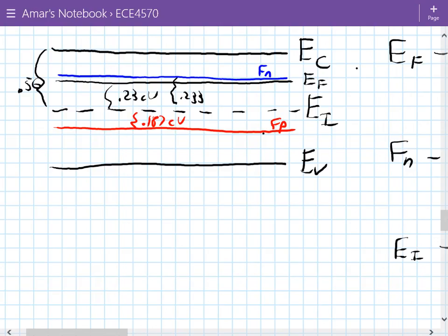What this diagram suggests is that the hole concentration changed a great deal. The hole concentration is below Ei, so there's a larger number of holes than the intrinsic hole concentration, which is 1.5 times 10 to the 10. The many electrons are also present, but not much compared to what there was initially. EF represents the electron and hole concentration after doping, but before irradiation from light.